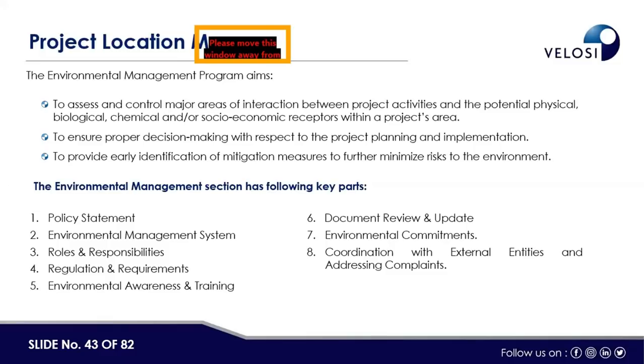So another question is, do you have a standard monitoring and evaluation tool for environmental impact assessment? It's monitoring and auditing on the basis of the project, and on the basis of the project structure or the resource structure, we can develop what monitoring and auditing tools we require to implement the EMP. As I mentioned, it is not a hard and fast rule. We have to see what the environmental impacts are, and then what the mitigation measures are, and what resources we require. Let's suppose the impacts are high and more negative, then we require more budget, more resources, and accordingly more monitoring and auditing. So it depends on the nature of the project as well, what resources and what monitoring and auditing tools we can develop for the effective implementation of the EMP.